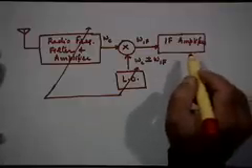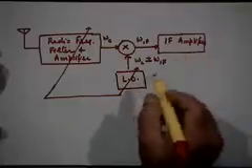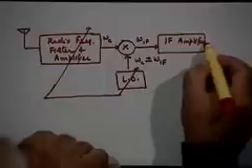Similarly, the IF amplifier can provide you high gain, right, because if this is at a fixed frequency, realizing such an amplifier with high gain is not a problem, right. And of course it can give you the fidelity that you want. Of course, most of the fidelity problems arise not at this stage, but at the power amplifier stage, which typically follows this, after you have detected the signal, right. So anyway,